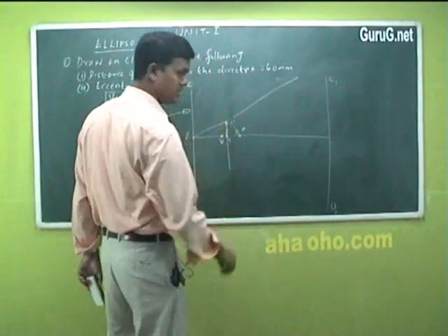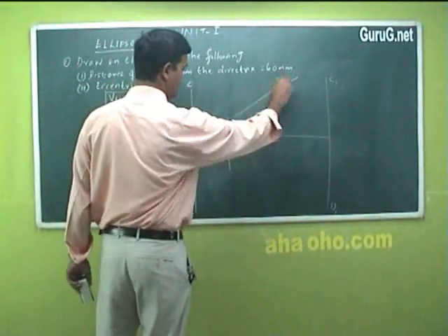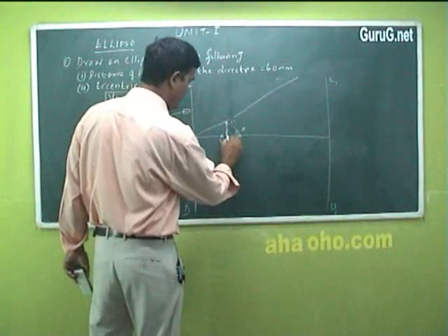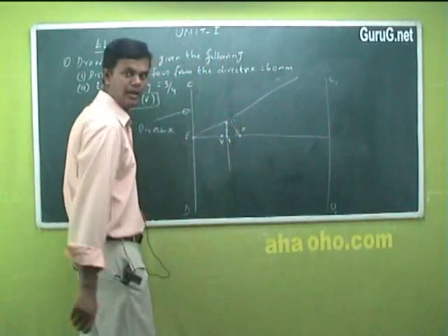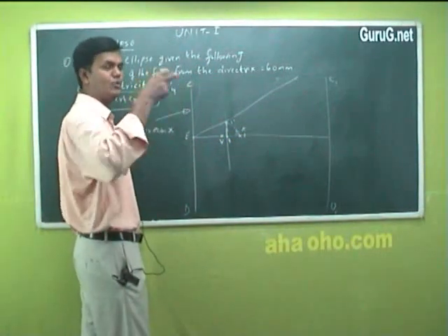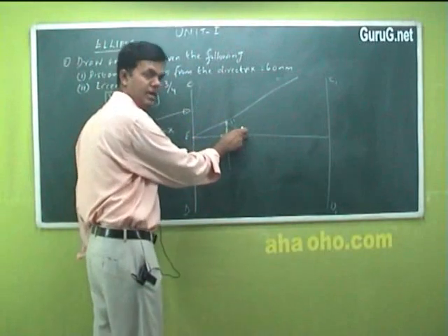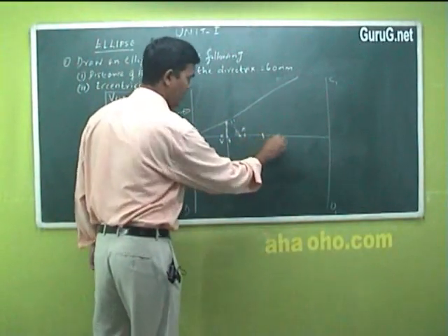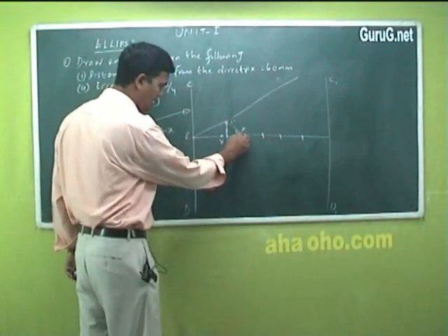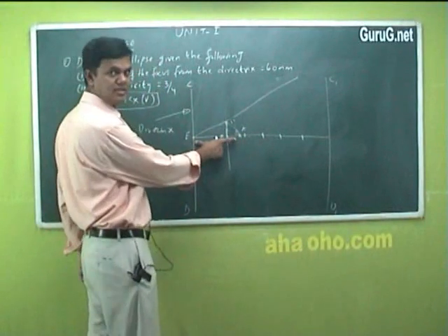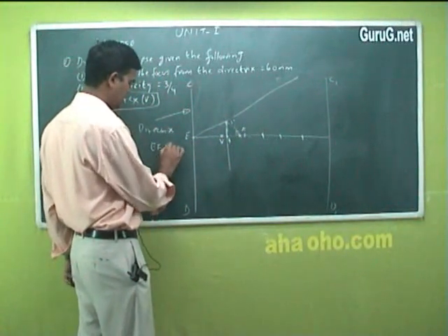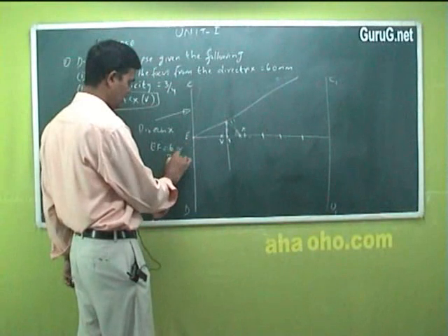Next step: after this, you have this curve, this line. On this line, you should take every point with the remaining part. Take point number 1 here, point number 2 maybe somewhere here. Take some in approximate distance. I will take 2 centimeter each. Another centimeter maybe here. And before this, you can even divide this focus distance, that is the EF value, into equal parts, say 6 or 7.